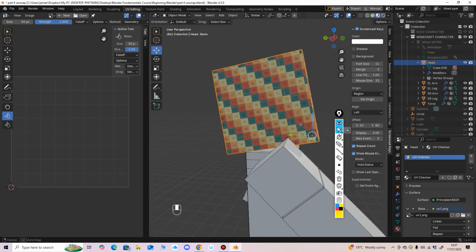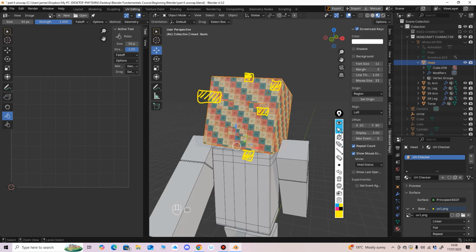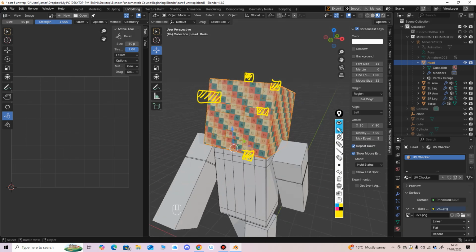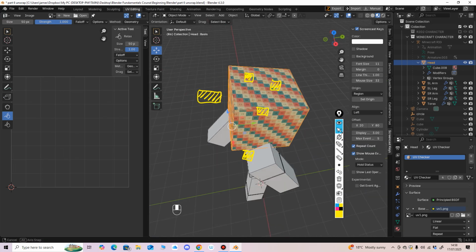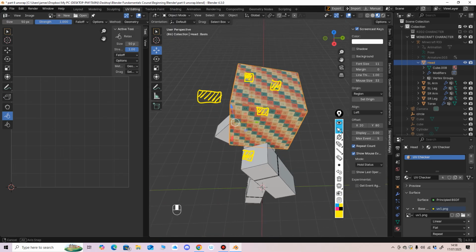And as you can see, like I've said, one of the things which is very important is that you've got a nice uniform checker pattern when you UV and stuff. And that's so things aren't stretching. Because if they're stretching too much, you won't be able to texture them or texture paint them to a decent standard.